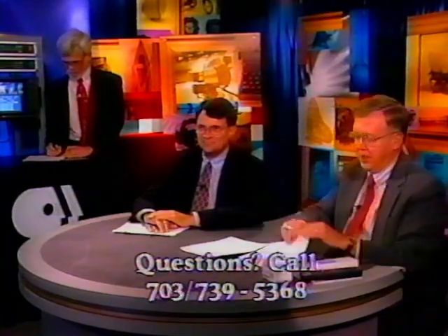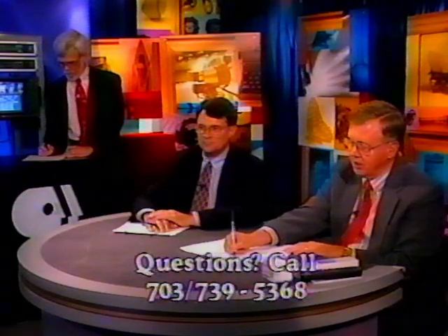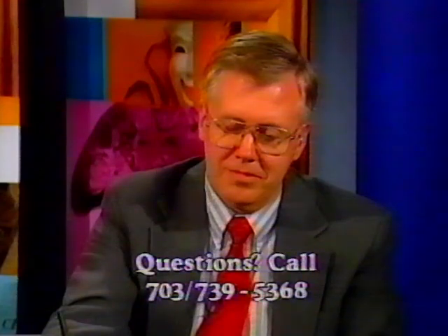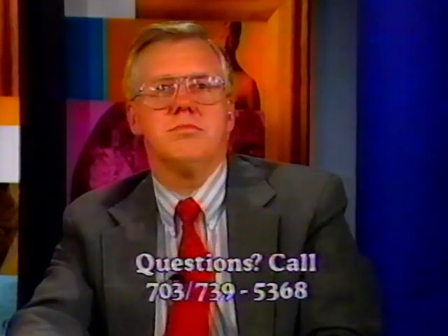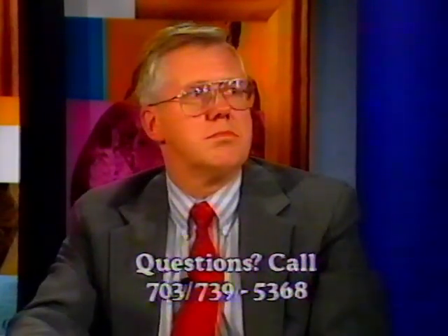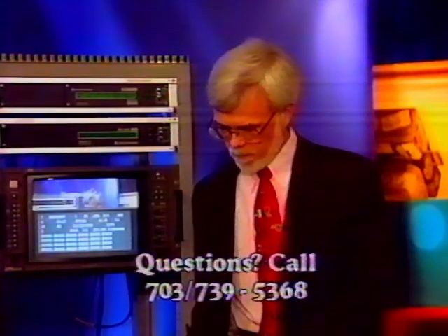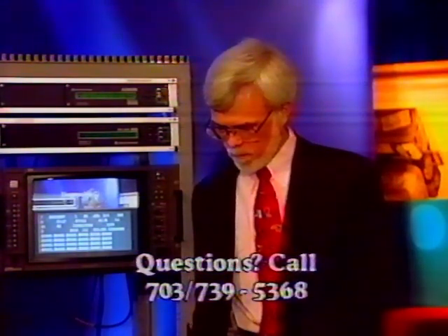Yes, how you doing, Ralph? I'm just fine, thanks. We're one of the test stations, and I have a couple of points of interest to the stations that haven't hooked up their 4000s yet. Go ahead. One thing, make sure your signal level is adequate. We had some problems with low or marginal level with our IRDs locking up, and we had flashes and such.